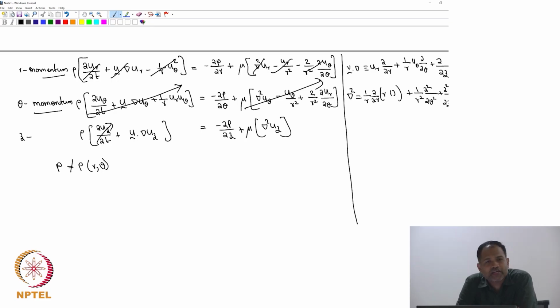How about u dot grad uz? This would mean ur ∂uz/∂r plus 1/r utheta ∂uz/∂theta plus uz ∂uz/∂z.